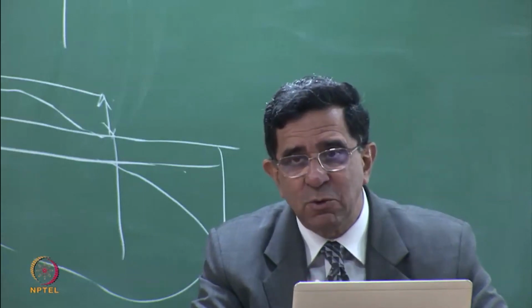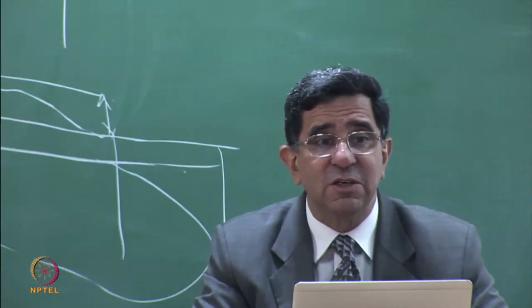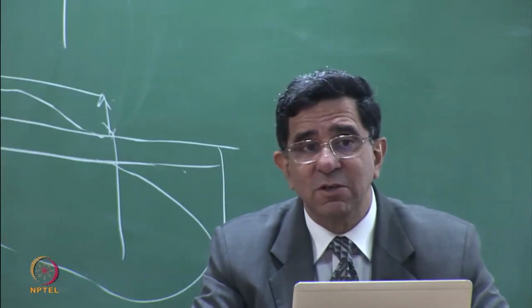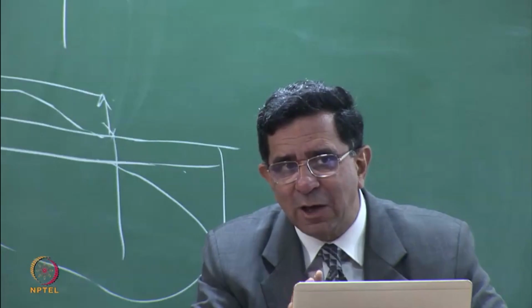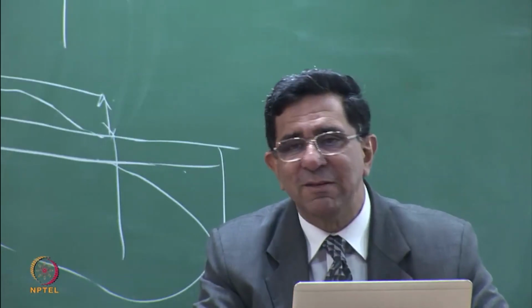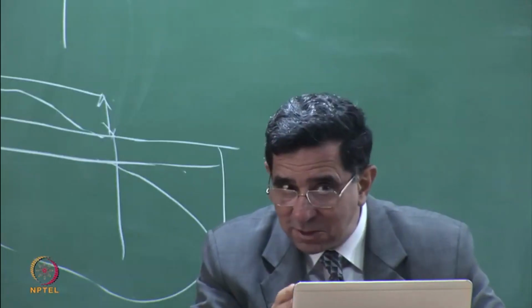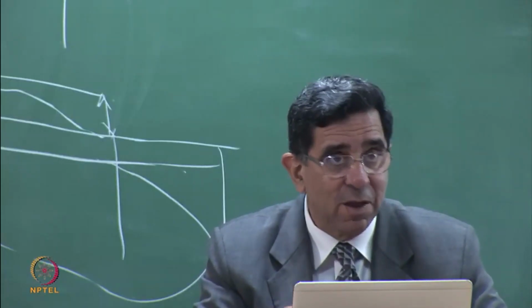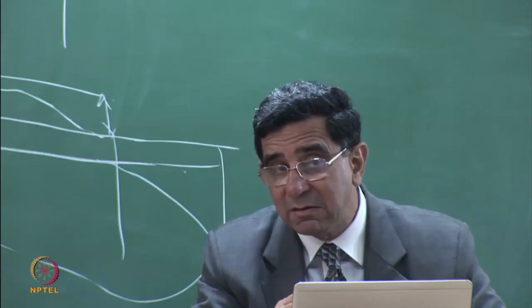And please differentiate between an undisturbed sample for site investigations for foundation design. What is an undisturbed sample for foundation design? The mechanical properties should not have got modified. It means your strength should be the same as in the field, your compressibility should be the same, and your permeability should be the same. What is a whole sample for environmental concern?